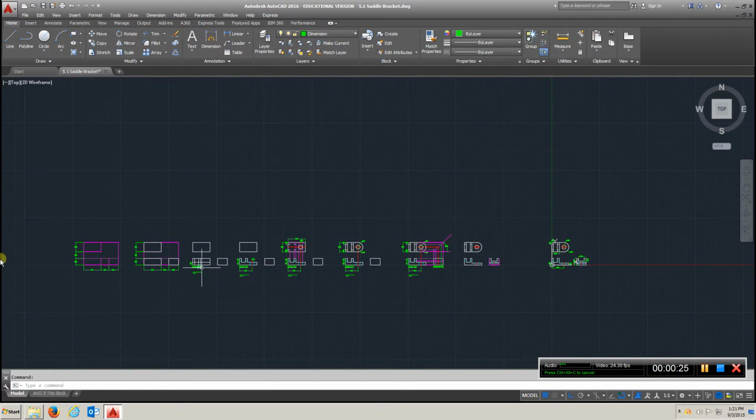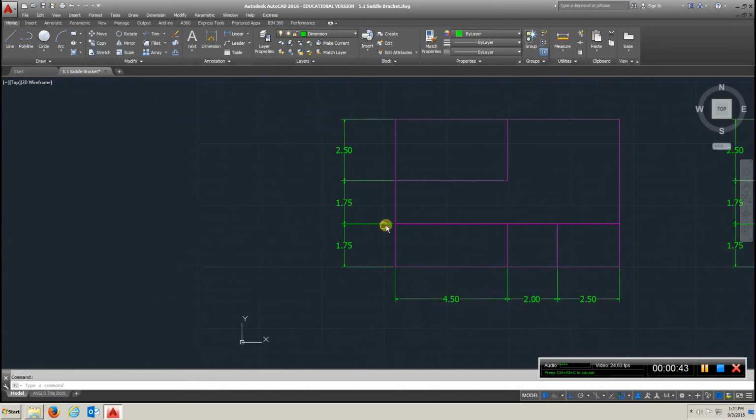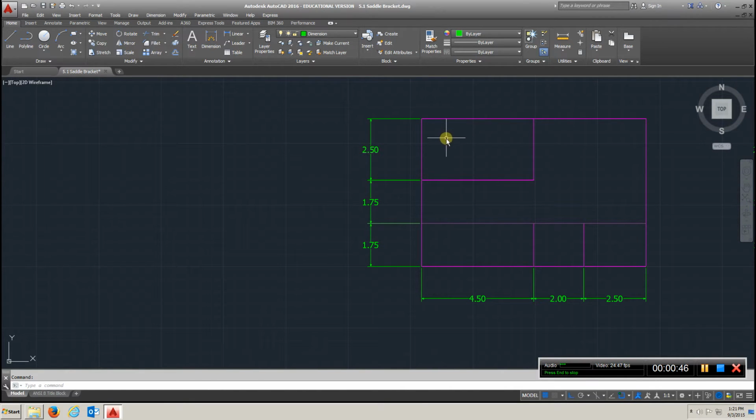forward I won't be showing you all of these procedures. You're going to just kind of look back on this one because it's always the same way to set this up for each drawing. Let's start here. Just like the previous video, you're going to create your box with your construction lines using these settings, and it won't be the same for each one because it depends on how wide the part is, what the depth is, and the height.